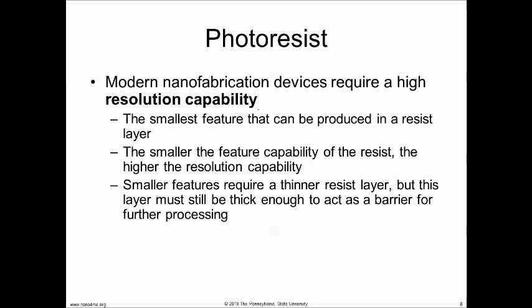So anyhow, this resolution capability is due to the wavelength of our emission source. For contact lithography, the most common source is the mercury vapor lamp. There are different peaks in this lamp, I'll show you later. But the peak that's the smallest wavelength with the best amount of energy is 365 nanometers. There's also one at 248, and that's a good peak, and it's even smaller, so you can make smaller devices. But the problem is the magnitude of that energy is about 20% of the 365.